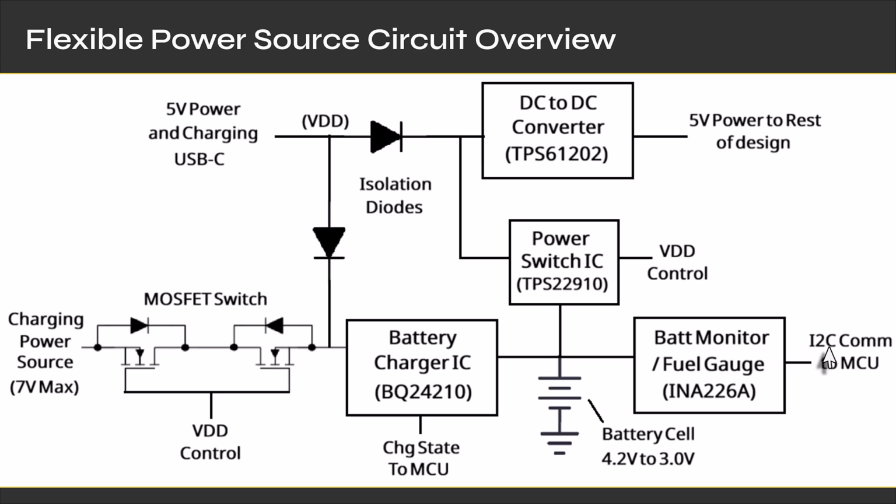Then, of course, I have a battery monitoring circuit here where I can measure the charge or discharge current of the battery and the voltage. I have that connected to my microcontroller through I2C. I also have a logic level from the battery charger IC to know when the battery is being charged and when it's not.